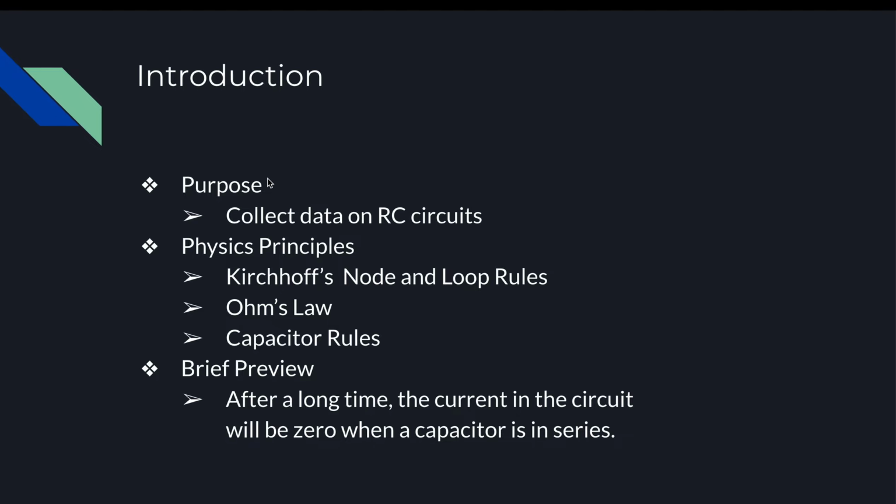Intro. The purpose of this lab is to collect data on RC circuits. The physics principles used are Kirchhoff's node and loop rules, Ohm's law, capacitor rules, and then a brief preview. After a long time, the current in the circuit will be zero when a capacitor is in series and it's charging.